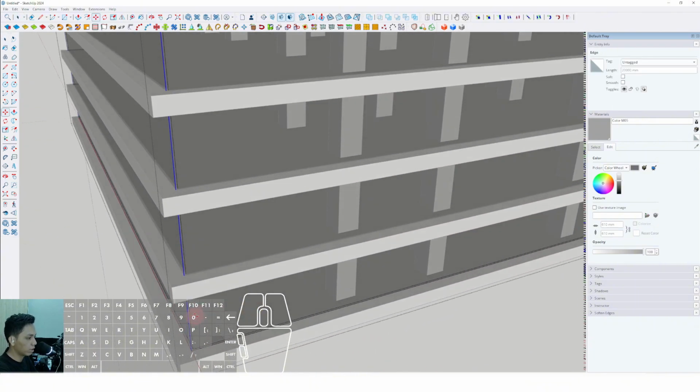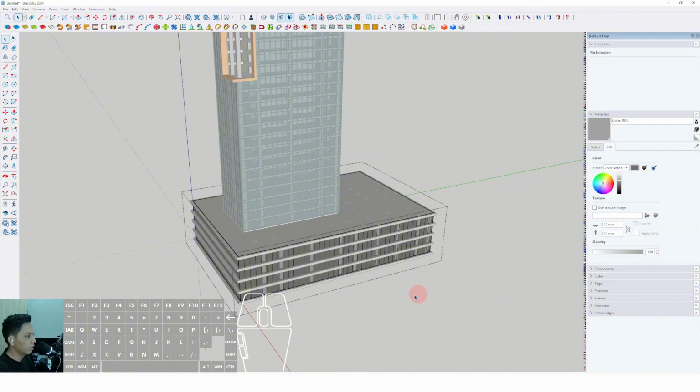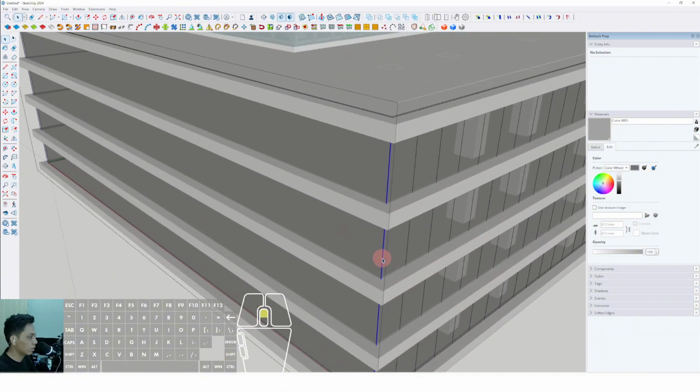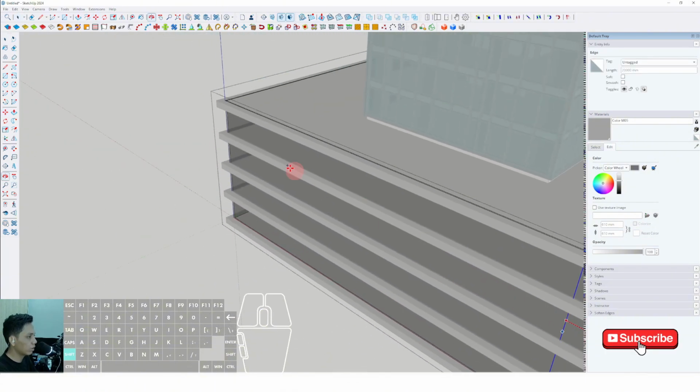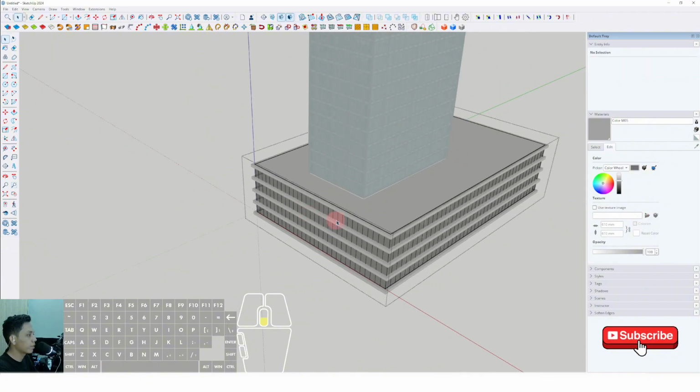You can select this line, select move, press Control, place it to this position, then type 40/enter. And also this one, select move, press Control, place it to this position, then we can type 20/ or maybe we can type 30/enter.